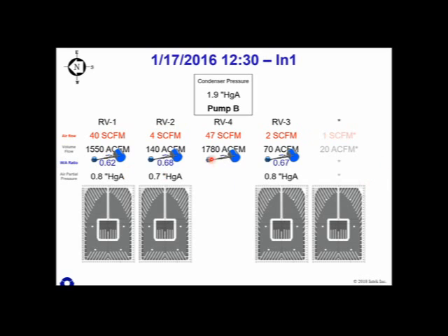Well, once we swapped the probe, everything continued to sum up, everything was in line, and started to explain the problem here. Just because you have a vacuum pump on the common line does not mean that that vacuum pump's capacity is going to be split evenly to all these bundles. And this is a very common occurrence, that when the air leakage is high to this bundle, the pressure tends to go higher here.